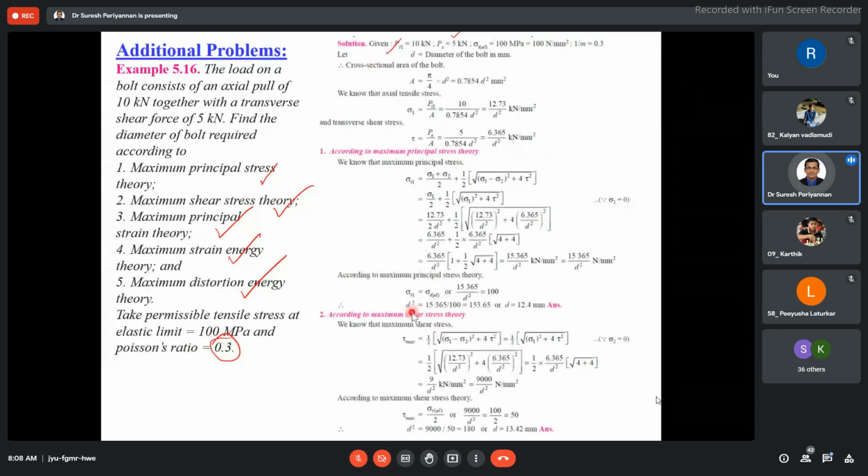come to the maximum shear stress theory. Similarly here, tau max is equal to the standard test specimen value, sigma critical divided by 2, that is 0.5 times SYT. That is what we observed and studied with the maximum shear stress theory concept in the hexagon diagram.